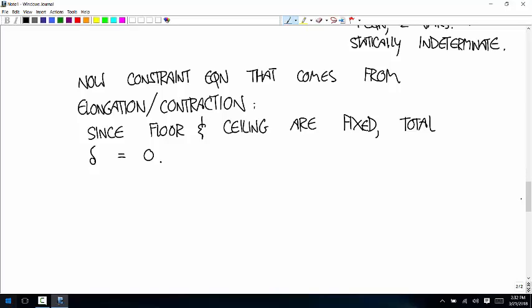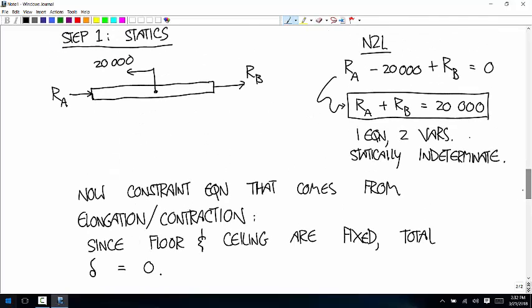Okay, so what are the steps for calculating the total? We've done a problem like this for the extension of an object before. The only difference was we had values for those two things before, right? But we're going to do it just the same way. We're going to calculate the internal loads in terms of RA and RB.